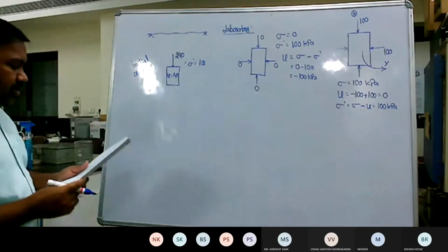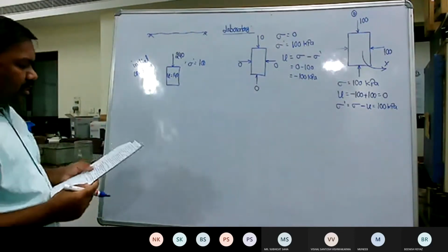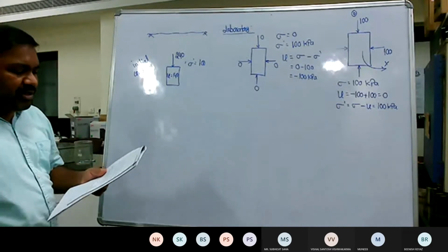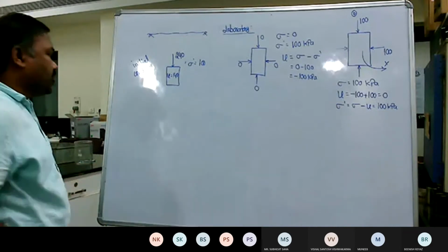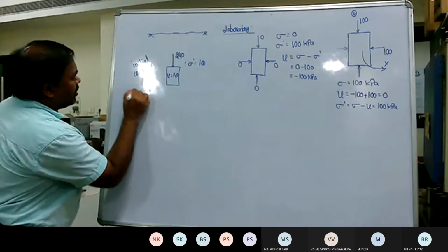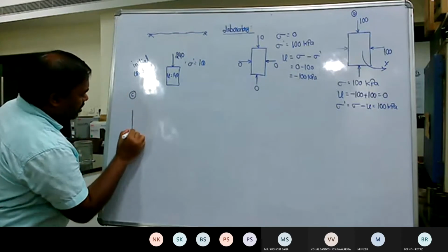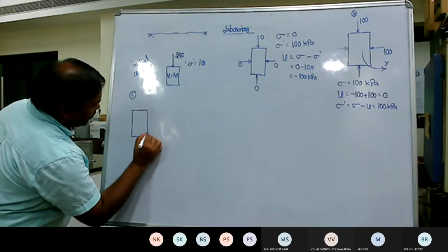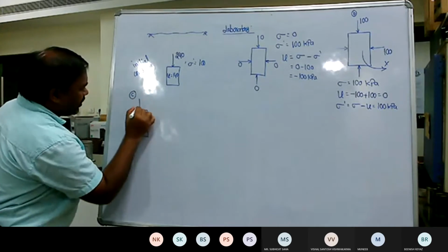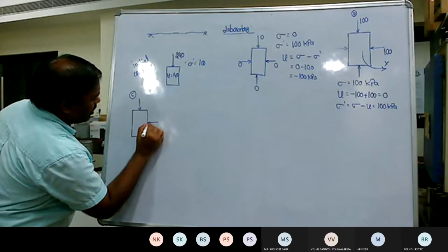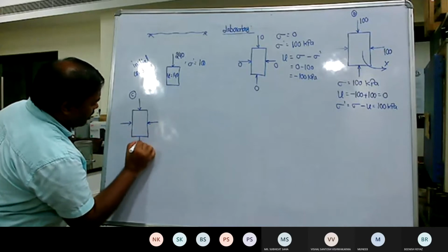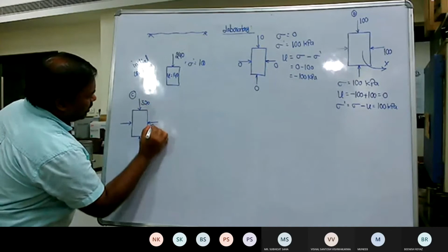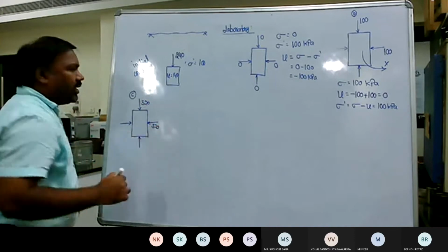Now go to the third point. The cell pressure was raised to 320 kilopascals with the drainage valve closed. So this is 320 uniform, that is, isotropic loading condition.